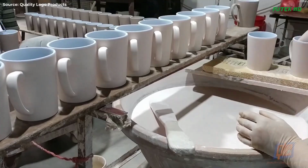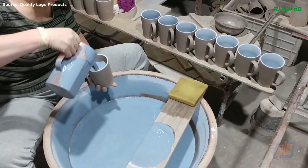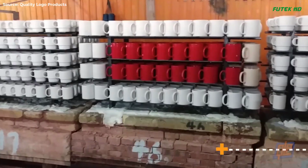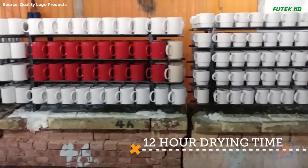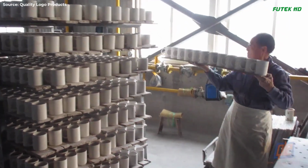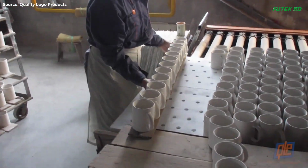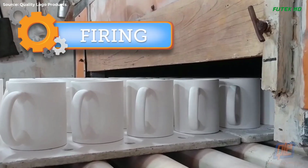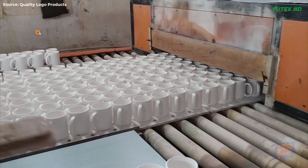After glazing, the mugs are left to dry completely for at least 12 hours. The dried mugs are placed on a conveyor belt that carries them through an oven, where they are fired at a standard temperature of around 2,200 degrees Fahrenheit. This high heat causes the mugs to harden permanently, giving them their durable and finished form.